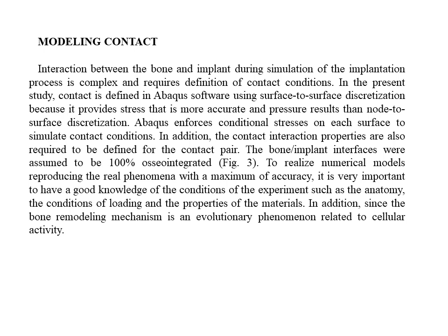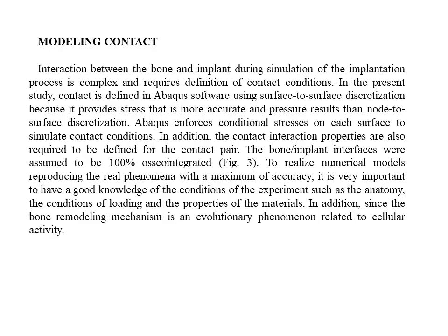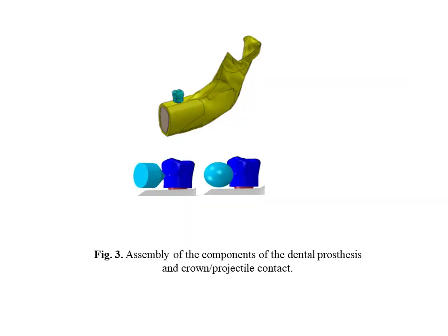In the present study, contact is defined in Abaqus software using surface-to-surface discretization because it provides stress and pressure results that are more accurate than node-to-surface discretization. Abaqus enforces conditional stress on each surface.